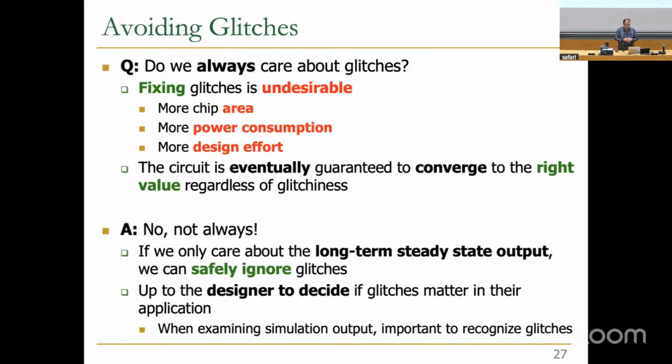But you remember that when I was presenting about Mealy and Moore machines, I said that Moore machines are better in terms of avoiding glitches. The reason is that in a Mealy machine, when you change the input, that input can also cause a glitch in your output. And that output might also be the input for some other Mealy machine, which can cause glitches in that machine too, and this can propagate.